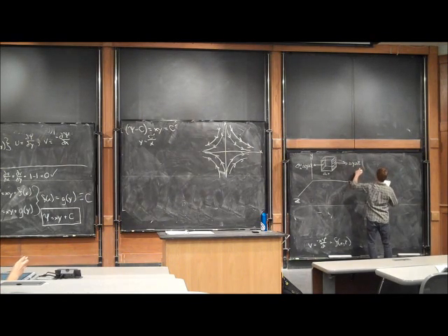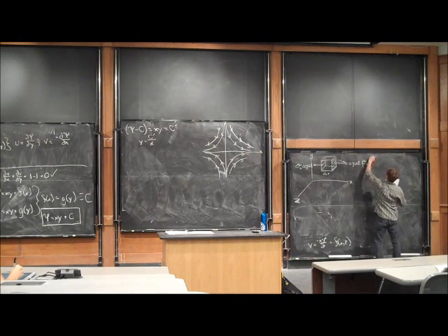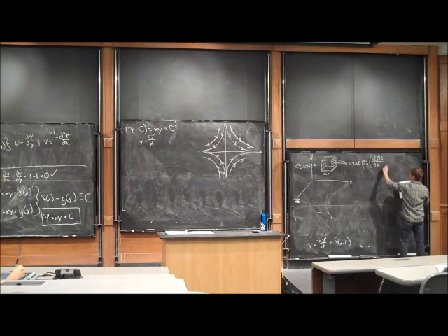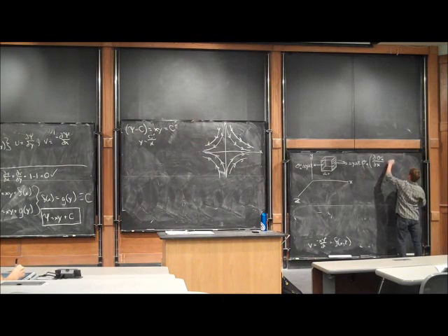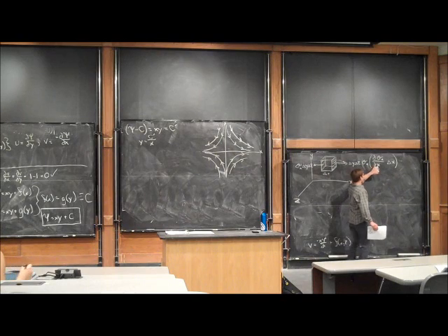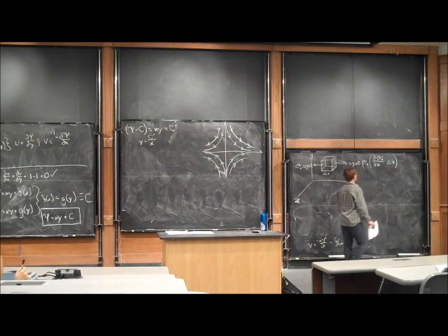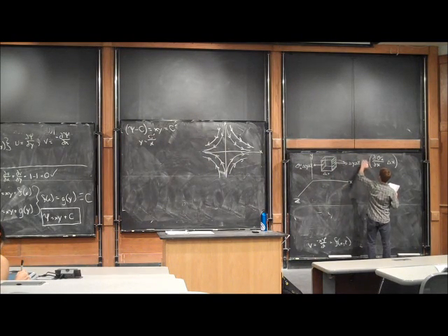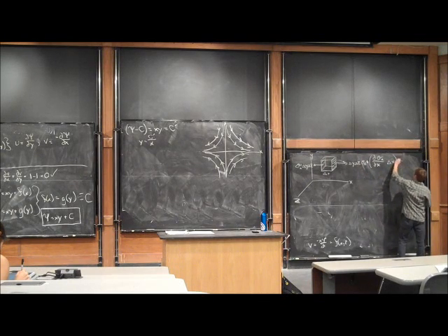So it'll have the same value, sigma x, plus how that stress changes with respect to the x direction times the distance. So if this is changing by some amount per unit length, times that length is going to give us the total change. So that's sigma x plus that, times delta y delta z.